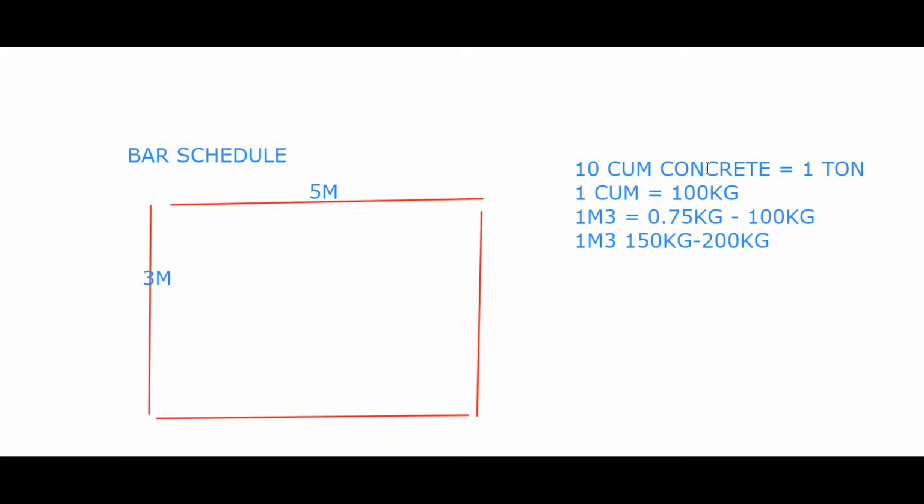What you only need to do is to use your worst case scenario. After getting your value, you can multiply by 1.1 or by 1.05, as in 5% for waste, for cutting, or 10%, and then another 10% for risk. So you multiply your value by 1.2. Most engineers don't do that. After getting your value for anything, assuming instead of asking for 50 lengths of iron, you ask for 60 lengths.